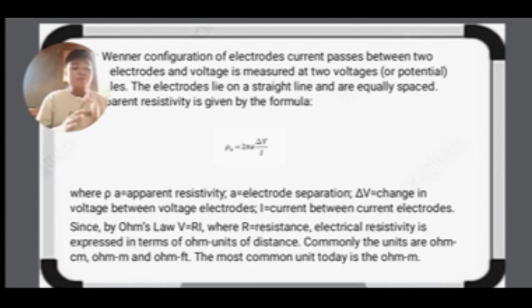However, if the ground under the electrodes consists of a layered series of materials of different resistivities, then as electrode spacing expands to give deeper current penetration, the measured apparent resistivity will also change. If the material is uniform but saturated below a certain depth, the water table level, then apparent resistivity will also alter as the electrode separation expands.